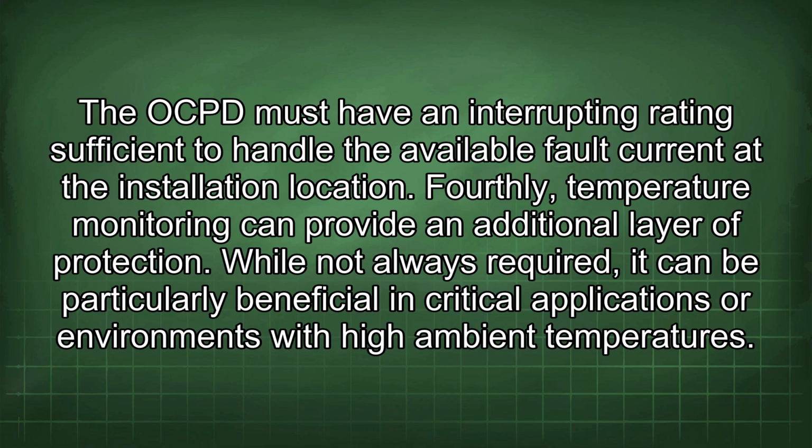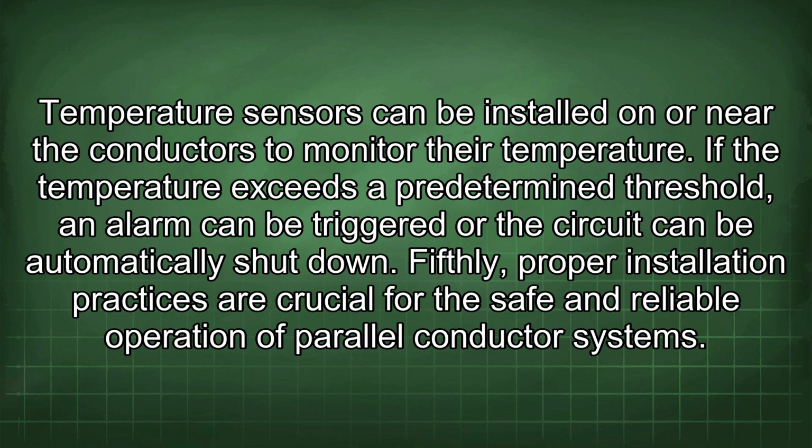Fourthly, temperature monitoring can provide an additional layer of protection. While not always required, it can be particularly beneficial in critical applications or environments with high ambient temperatures. Temperature sensors can be installed on or near the conductors to monitor their temperature. If the temperature exceeds a predetermined threshold, an alarm can be triggered or the circuit can be automatically shut down.